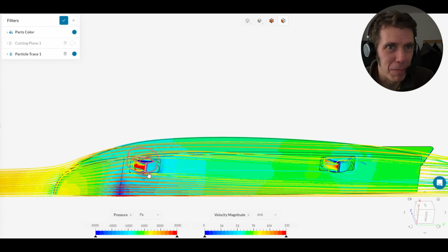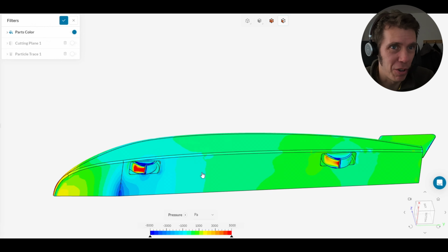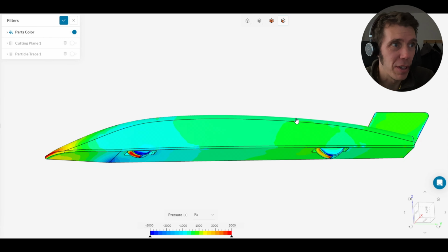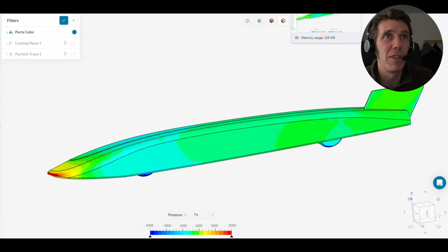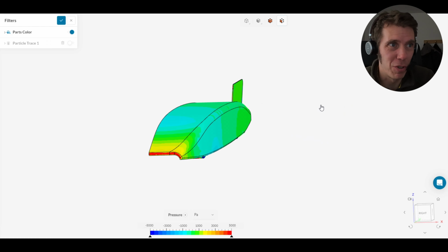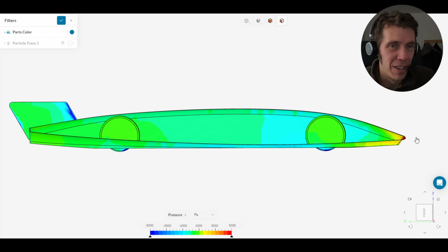We're going to see a common theme for all of these plots, that the tyres light up as an area of high pressure, but I found there wasn't really a lot I could do about that. So that's the flat bottomed one, and then I'm going to show the first more funky shape design that I tried. This one was taking that idea of an underside wing into the design and analysis. You can see there's a bit of a throat formed underneath the car. It starts off higher, goes lower to the ground, and then goes higher again towards the rear.